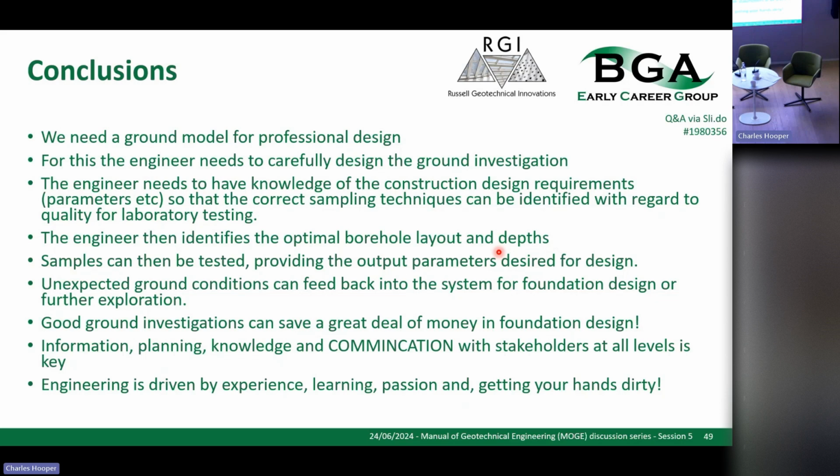You actually need to know quite from the start the samples that you're going to need to take, possibly the number of them. But I fully understand this revolves around money, and we all do the best that we can. But it's the sample quality of what you need. If you're using finite elements analysis to design something, you really do need good parameters, because it's relying on those, and that is what the very high end triaxial effective stress tests can produce.